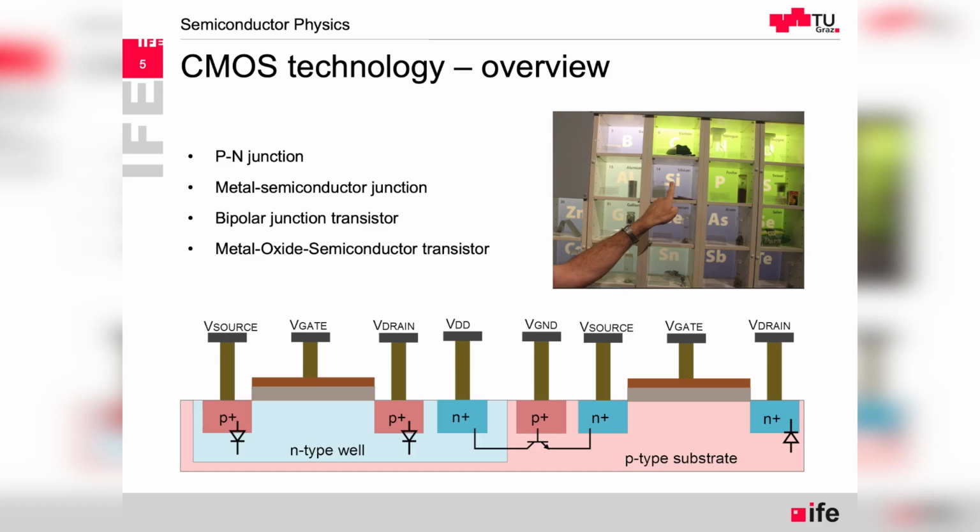And very important, we also have this metal semiconductor junction, which can be, as we know already, a metal ohmic or metal Schottky contact. And we have this every time that we contact with metal. So just in this slide, we see several contacts to silicon, and each of them is exactly such a contact, which shows how important it is to tailor the right characteristics of the junction to have low ohmic resistance, providing a good conductivity between the conductive interconnections and the silicon devices themselves.